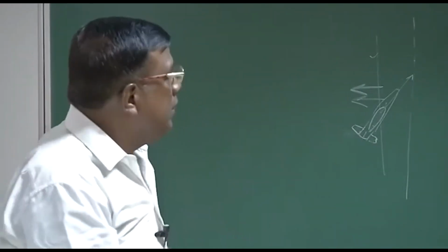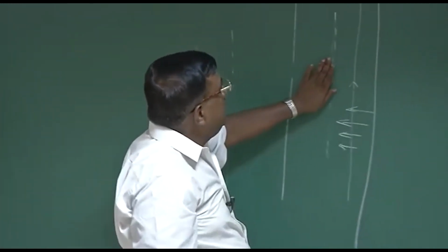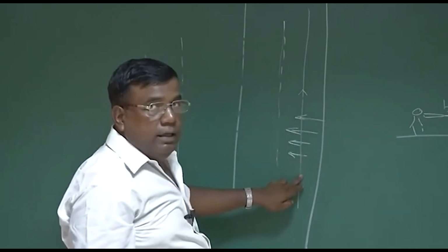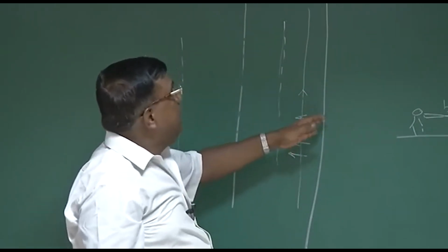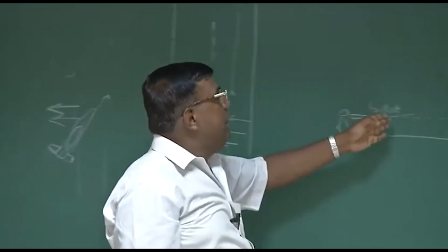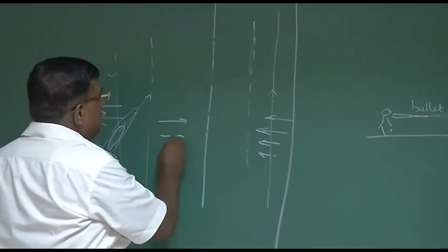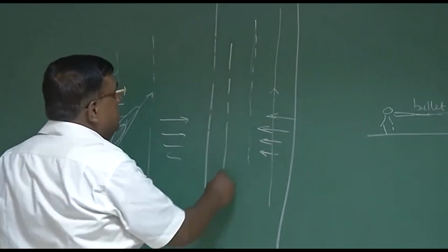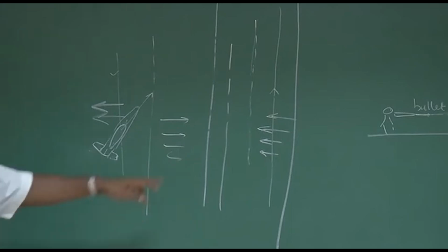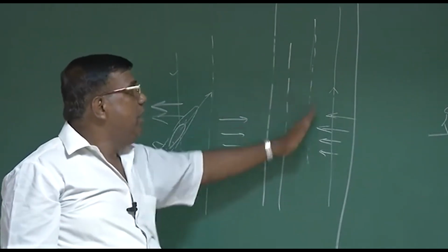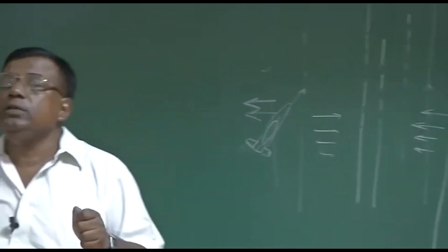This is one way. So what is that way? If I want to land here, and I know wind is coming from the right hand side, I will be aiming at some other line here, knowing very well I will be drifted back to this, like the example I have given here. Similarly, if wind is coming from this side, I will create an imaginary line here. I will approach this as the central line where I am going to land, and because of this wind, I'll automatically get drifted and come near the central line. So the pilot, with visual aid, if they are not flying through the instrument landing system, will be applying corrections.